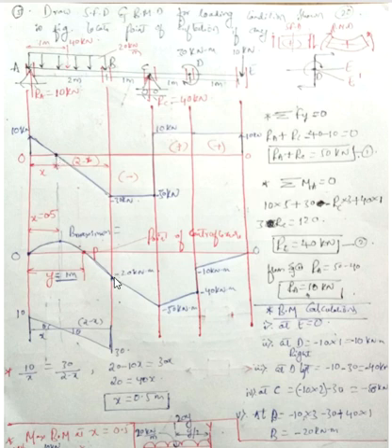So instead of joining curve from this point to this point, wait for a second and calculate the maximum bending moment at this section, because shear force at this point is 0. Now to calculate maximum bending moment, I need to first know the distance x. For that, I am going to consider this triangle and this triangle, which I have already explained. Height at this triangle is 10, and I have taken this distance which I need to calculate as x. Here I have written x.